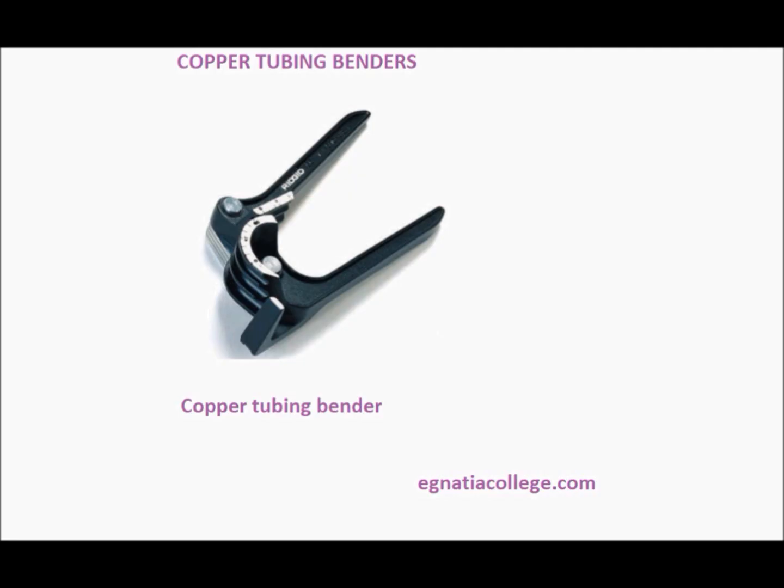However, this skill is required for many exposed connections such as sinks, tank-type toilets, and other equipment with a small diameter water supply. Soft copper tubing can kink if it is bent by hand with too small a radius, but the bending tool creates compact offsets.